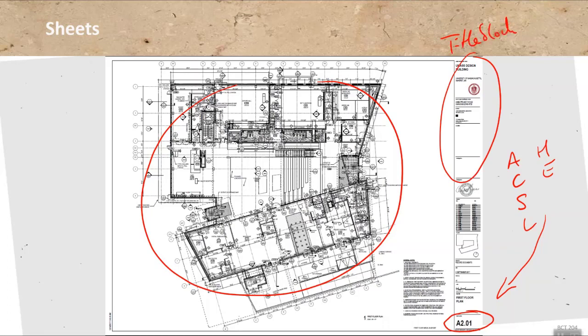And the title block can have different designs again. Typically it also has a border around the entire sheet, which you see up here, of course, and then contains a ton of information. So this is where you find the number, as I just showed you. You'll find the title of this particular sheet, what it is, what's on it, floor plan, for example. You'll find something about the project and some details about that, typically who the client is, etc., all of those kinds of things.